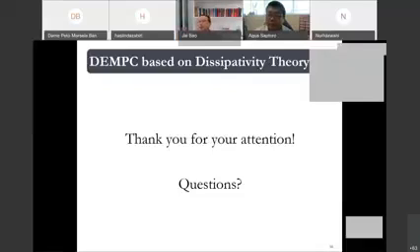And in that case, the problem is very, very difficult to solve because it becomes NP hard. It's non-convex. But because we use dissipativity conditions, and we don't use the models directly, we use the dissipativity conditions of each individual subsystem, then the overall stability condition becomes a linear condition. We can solve that using linear matrix inequalities. So it becomes a convex problem. It's actually quite easy to solve.